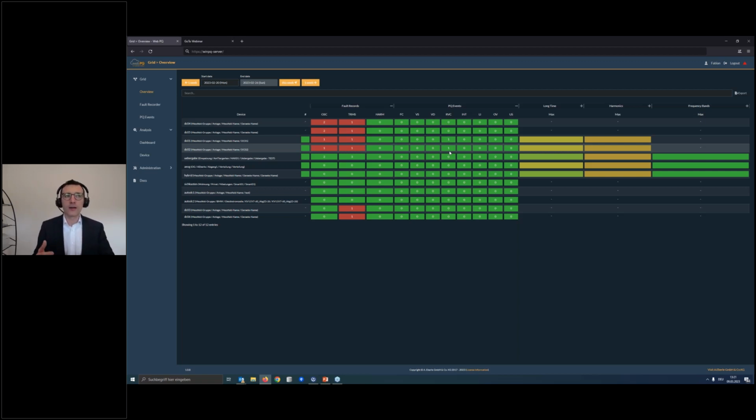So if a fault occurs in a grid, for example an earth fault, then our meter internally stores a very high accuracy and very long disturbance fault recording. In the meanwhile, we can record up to 160 seconds of samples in an oscilloscope recorder, and 6 minutes of true RMS, 10 millisecond true RMS recordings in one DFR. And this can be seen here in the field fault records.